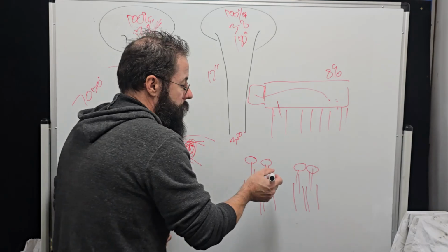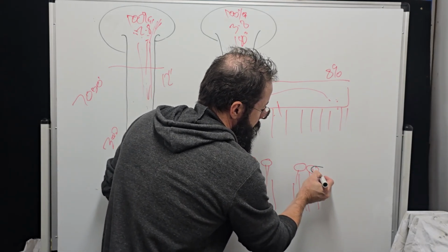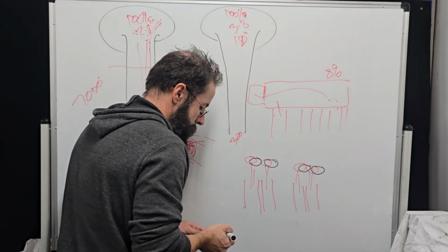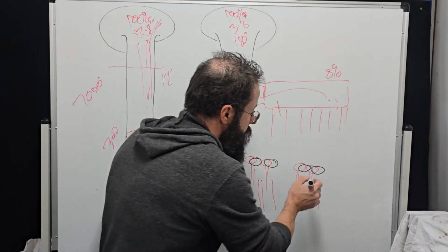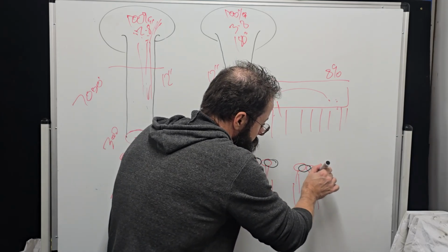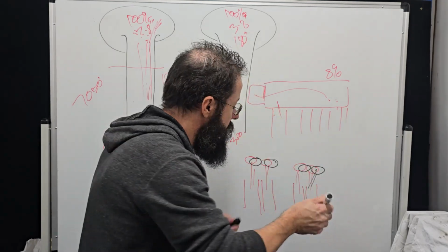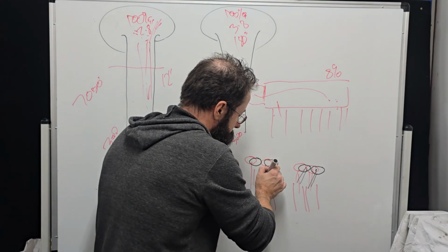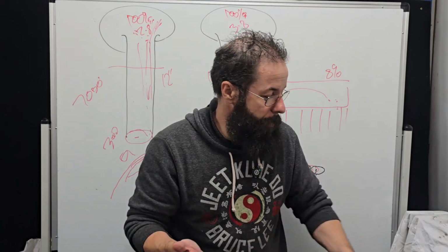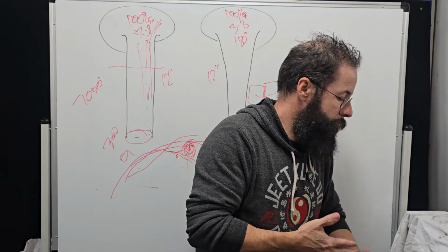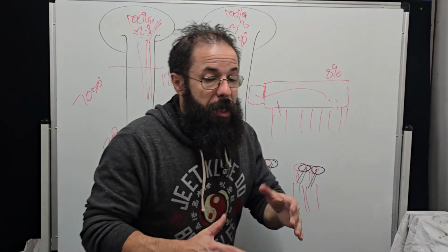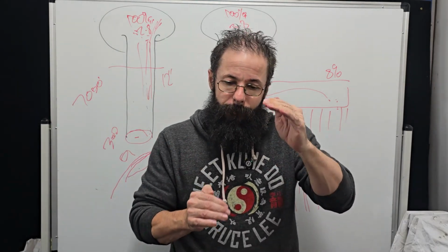what we do with some really, really quick cars is offset the top plate, and now these are in front of the runners. The reason we do that is because we're fighting G-force. Just like a blower tends to throw to the rear, the fuel is going to fall because the fuel is heavier, 100 times or whatever it is, heavier than air. It's going to want to fall backwards slightly. So we actually offset the top plate slightly. Again, we'll lose horsepower on the dyno, but at the track you'll pick up a few mile an hour.